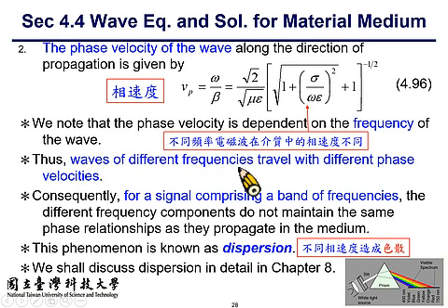All right, and here is the expression for phase velocity, Vp. The subscript p refers to phase. This is the so-called phase velocity, which is defined as omega, the angular frequency, over beta, the phase constant, and it can be represented as this number. As you can see, the phase velocity is also associated with the loss tangent, which means that if the loss tangent is non-zero, if the conductivity is non-zero, then the phase velocity can be a different number for different frequencies. All right?